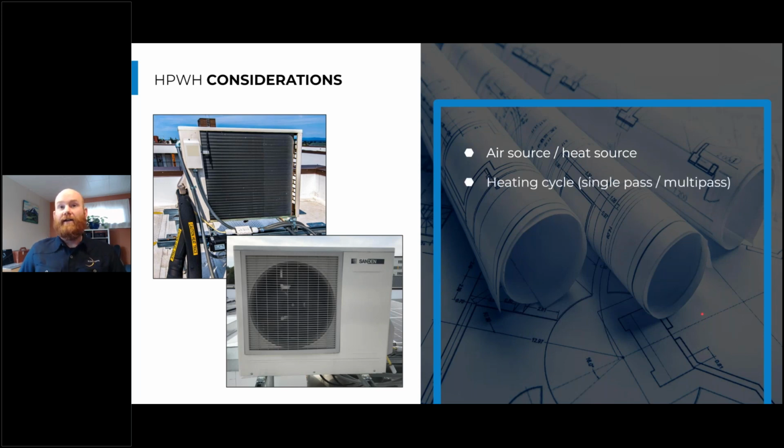The heating cycle is also a consideration that you need to be aware of, whether it's designed to be a single pass heater or a multi-pass heater, and whether you can change between those in practice. Some manufacturers and technologies allow that. Others, like CO2 systems, are only going to operate in the single pass mode. And that ties back to the refrigerant used in that refrigeration circuit.